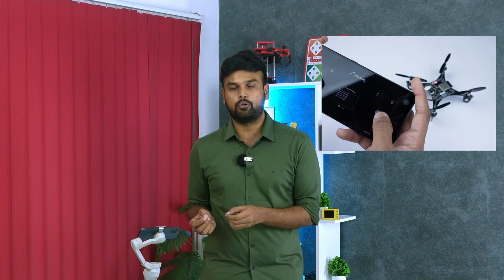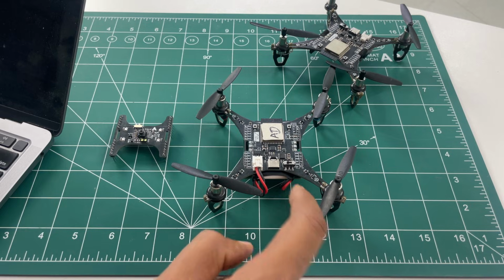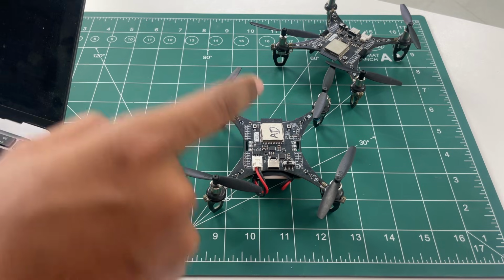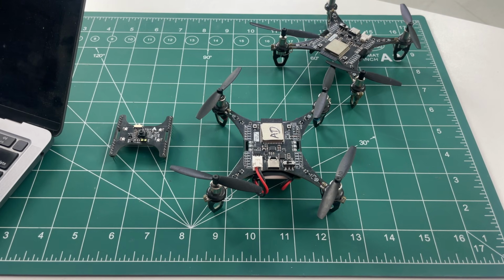Way number one is pretty straightforward. Right out of the box, power your drone on, connect it to your mobile phone app and fly it directly from there. That is a very basic approach where you can just fly your drone. The second way is more complicated. You can use the onboard Type-C connector that is shown over here, not only to charge this battery, but also to program the ESP32 microcontroller that you can see on the drone. So you can connect the drone to your laptop and use Arduino IDE or ESP IDF to write the complete flight control firmware from scratch.